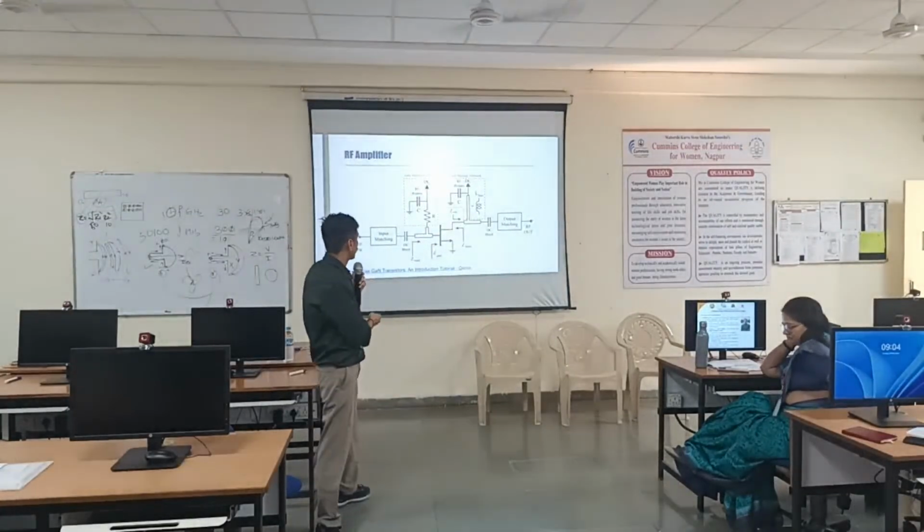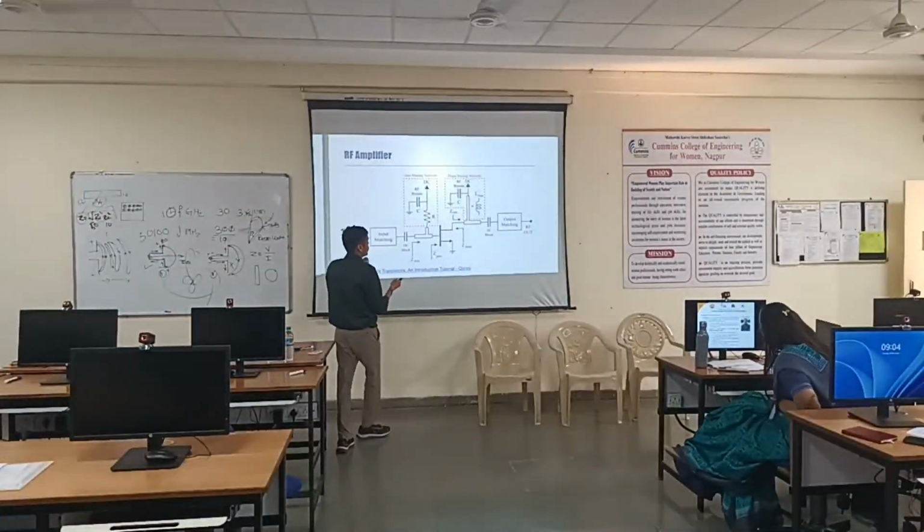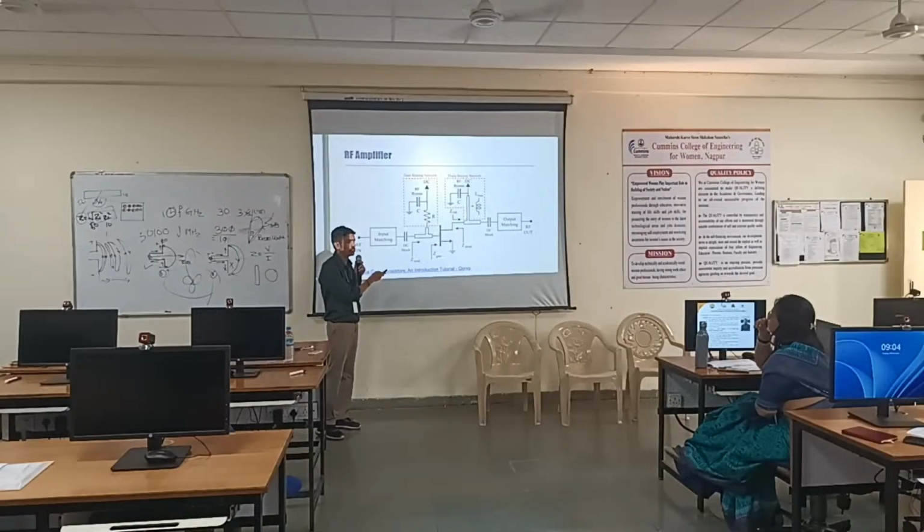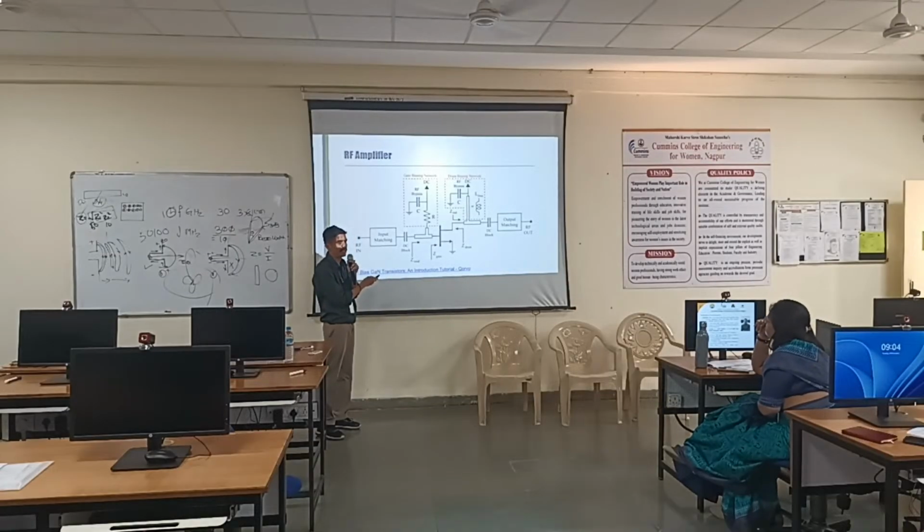Okay. So the DC signal, let's say some ripple is coming over here. That ripple should not come here. Means if this is the short point, what is the only solution? This point should be open for that ripple. And it can be done with the lambda by 4 line only.